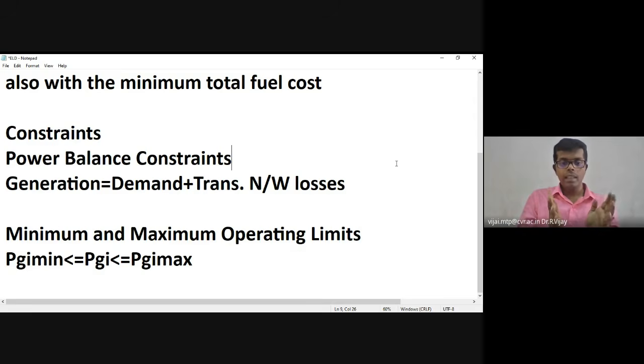Like that only, the generator runs based on its design. If you are running at a very minimum speed, say in the nameplate details they have mentioned you have to run at this much, but you are running at a very low speed, then in that scenario also the losses might be more and the efficiency will be very low. At that efficiency you are spending more water, more water coming from the upper stage of the dam to the lower stage of the dam.